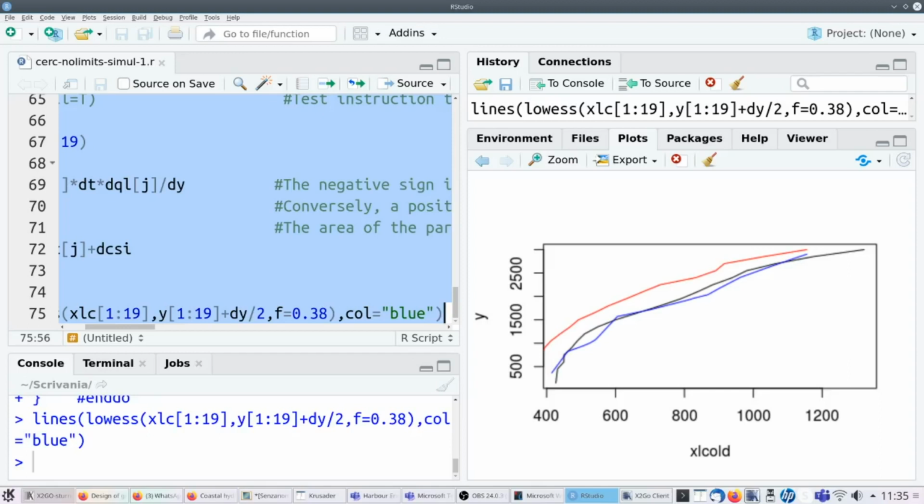Maybe I have to reduce the length of the time step, because instability may also be given by a numerical approximation, and numerical approximation is reduced if you reduce the size of your spatial and temporal steps. So this is something that you have to carefully evaluate.